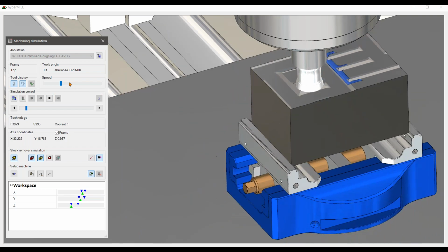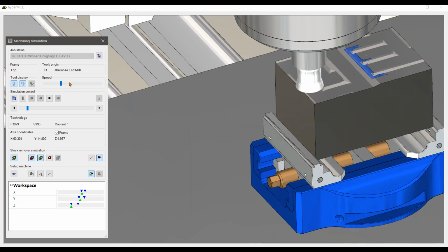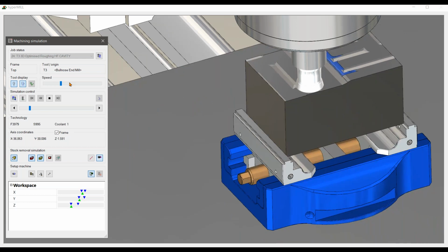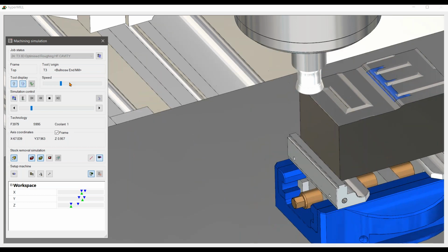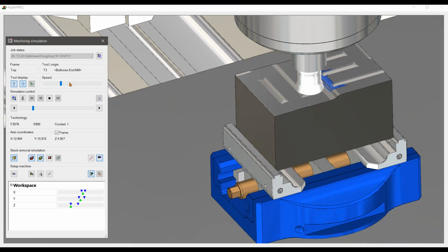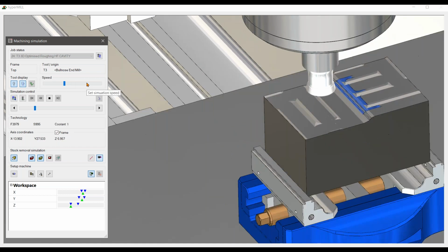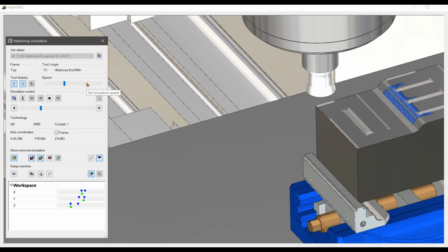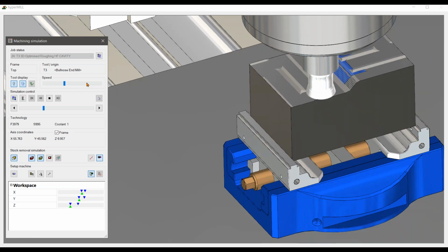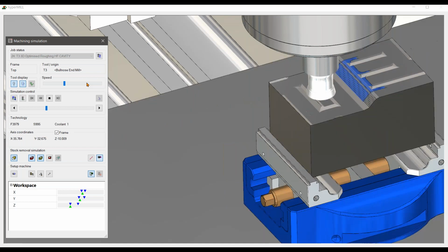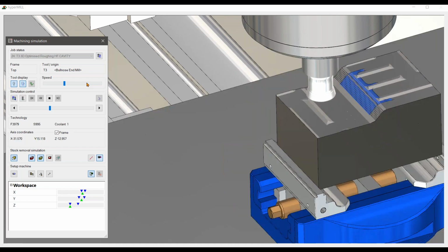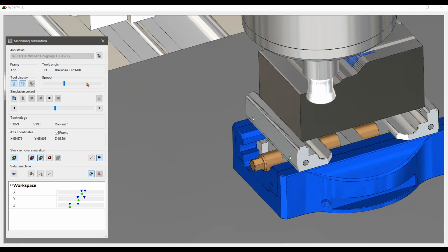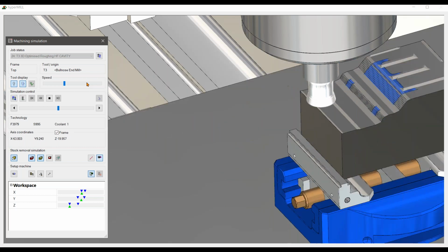You can see it's adapted itself to a pocket. It's constantly looking at the stock scenario to find out what's going to produce the best result here. Now, typically, you've seen a lot of tool paths. Yes, with high feed machining you are reducing your step down drastically. However, these tools are doing millimeter-plus per tooth metal removal rates, and it's incredible.